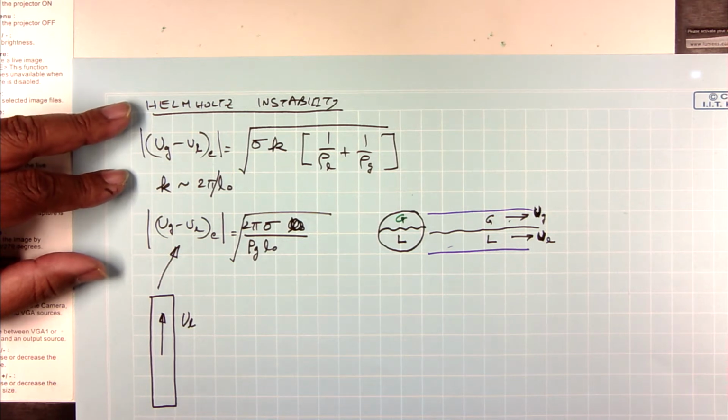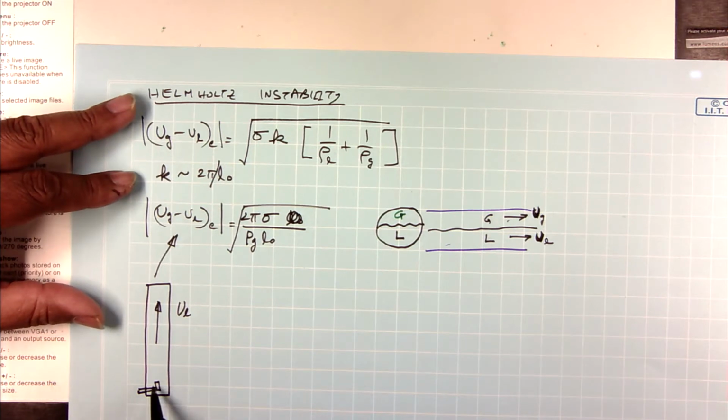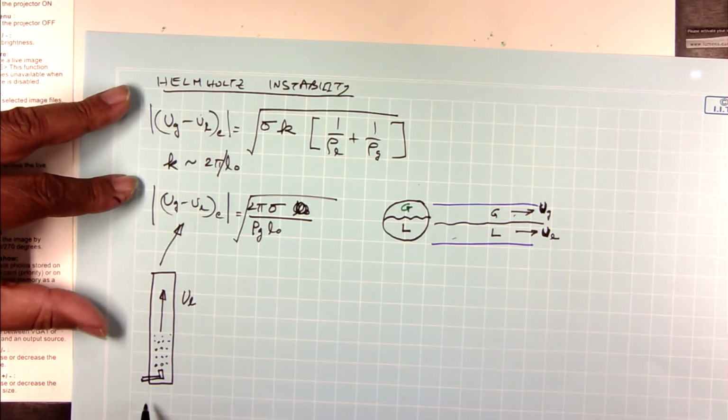Okay. Now I can introduce a small nozzle, and the shape of the nozzle, the size, whether it's porous or non-porous, all these things will affect your answers. But let's just forget about those complications. Let's assume how you introduce the gas phase doesn't matter at this point, and let's say you introduce air at a very small flow rate. So you are going to end up with small bubbles that form in the flow, and they will sort of orient themselves homogeneously around the cross section of the pipe. So you end up with what is known as bubbly flow.